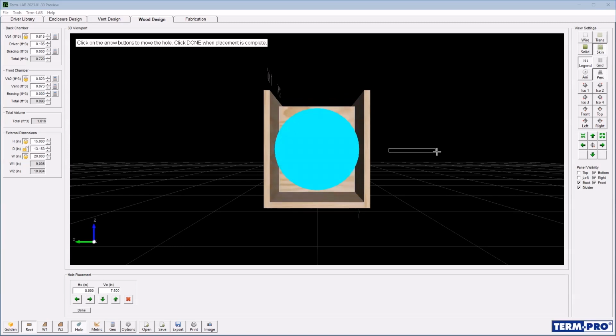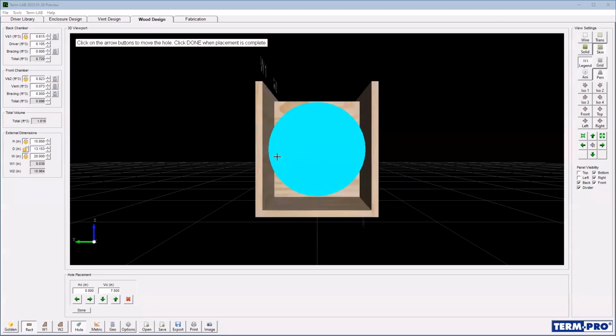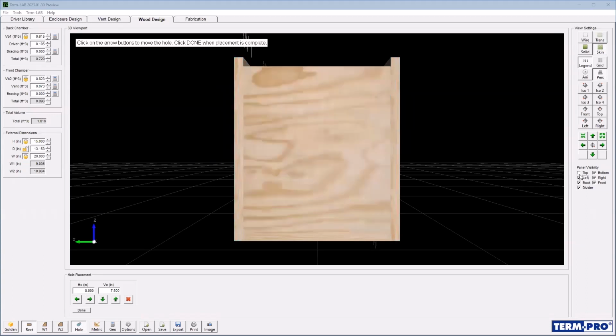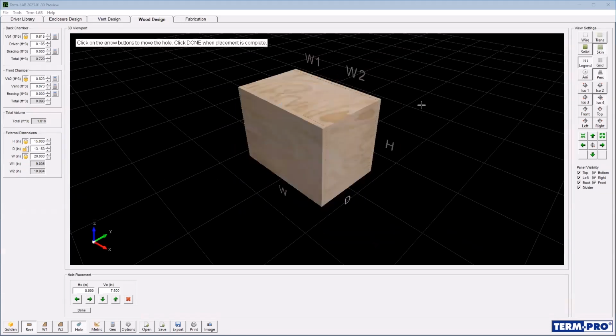Ooh, this is not going to work because this is the hole size, and you can see that it won't impact, but the flange isn't going to work. So it's back to the drawing board here. This is the kind of stuff that you really need the software to do. So let's unlock this, and let's change this to 18 inches.